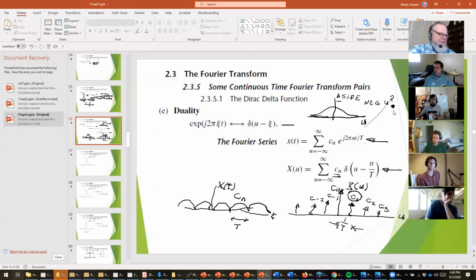Yeah, that's an excellent question. I think, Aiden, what we do is kind of dictate the area under the delta function in an indirect way by the height of whatever that arrow is. So you notice that the C0 has a height which is different than the C1. Now, both of them go to infinity, but it's just kind of a way to code that the C sub 0 has a bigger area than the C sub 1. So we kind of modulate it that way. It's just a way of expressing it. Does that answer your question? Yeah, that makes sense.